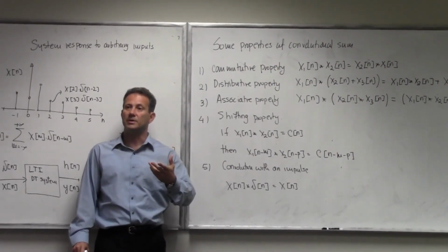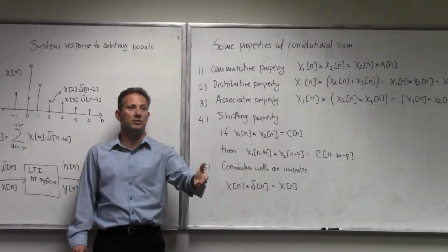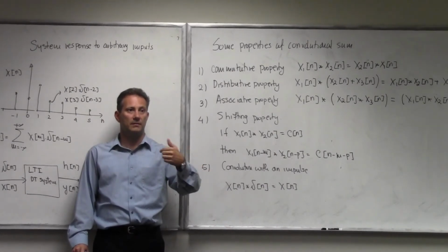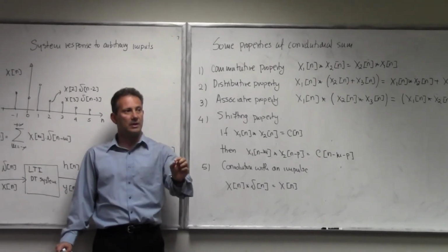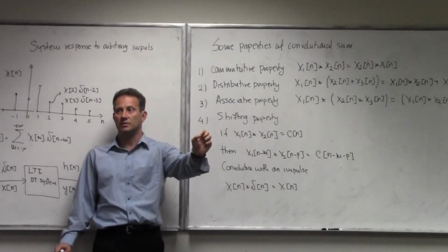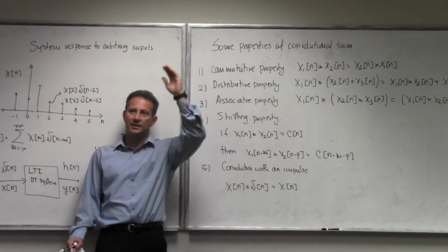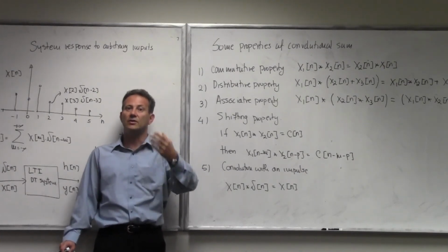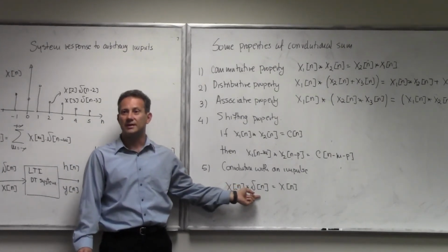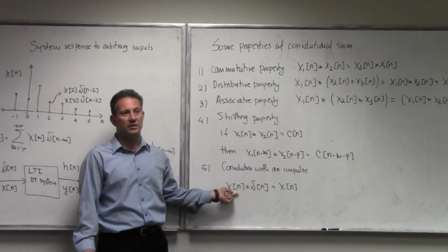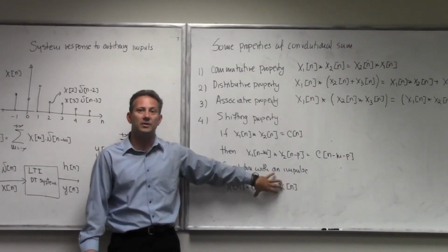What does an ideal filter impulse response look like? Well, we can think about it. If I feed an impulse, what do I get at the output? If I have an ideal filter that just lets the signal go through, and I put in an impulse, what am I getting at the output? I'm getting my impulse back. In general, we allow scaling and delay, but the thing is, you're getting your impulse back. So the filter that has impulse response equal to an impulse is an ideal filter. And if you feed this filter with an arbitrary input, you're going to get your input back. That's one way of interpreting this equation.